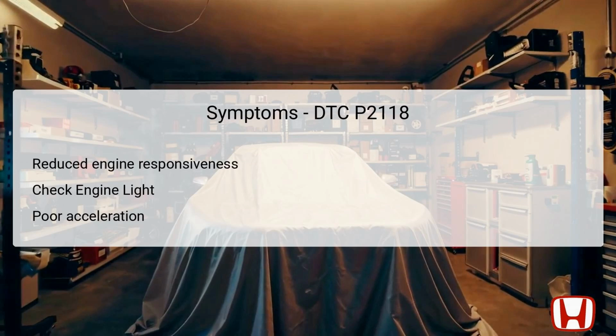In the presence of DTC P2118, several symptoms may manifest within the vehicle's operation. One common symptom is reduced engine responsiveness. The driver may notice that the engine does not react as expected when the accelerator pedal is pressed, potentially resulting in unsafe driving conditions.